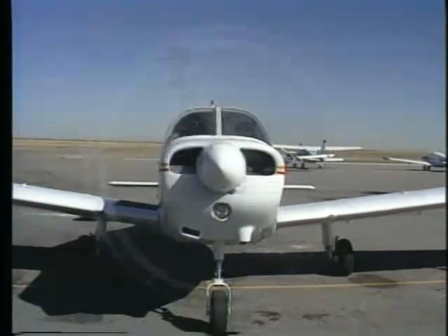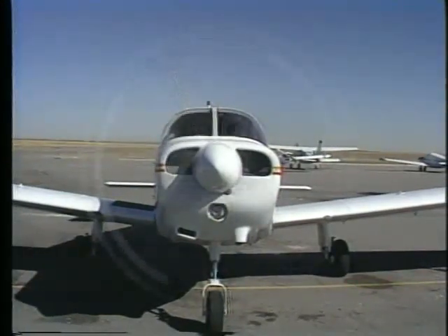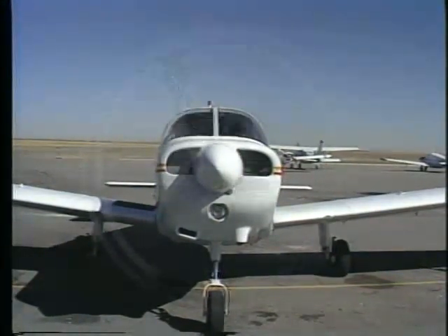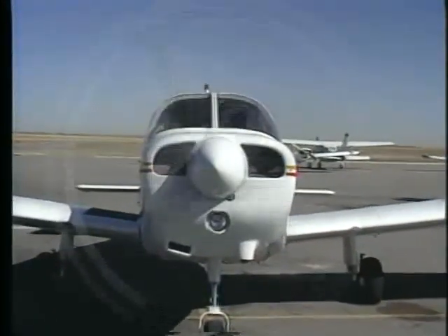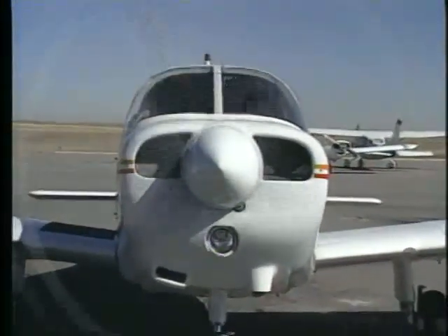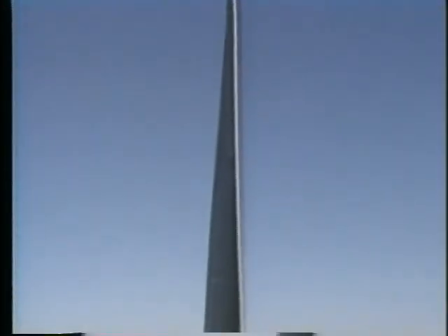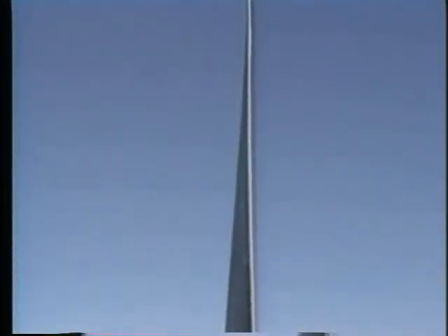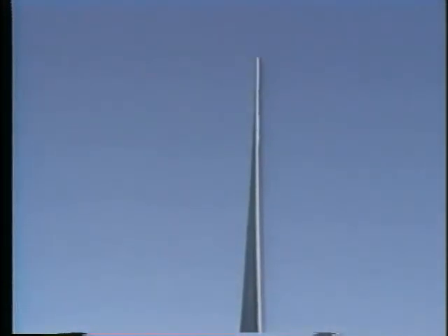However, unlike the wing, which is traveling at a uniform rate in straight and level flight, the tips of a propeller are traveling through the air faster than the area near the hub. Therefore, a propeller blade is twisted with less angle near the tips. This creates uniform thrust along most of its length.